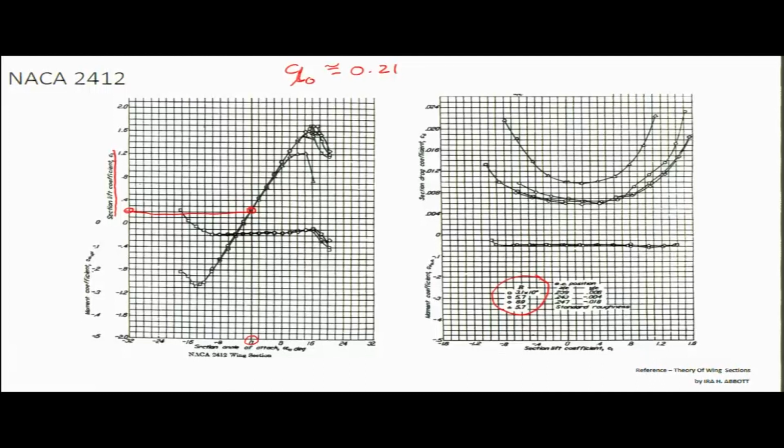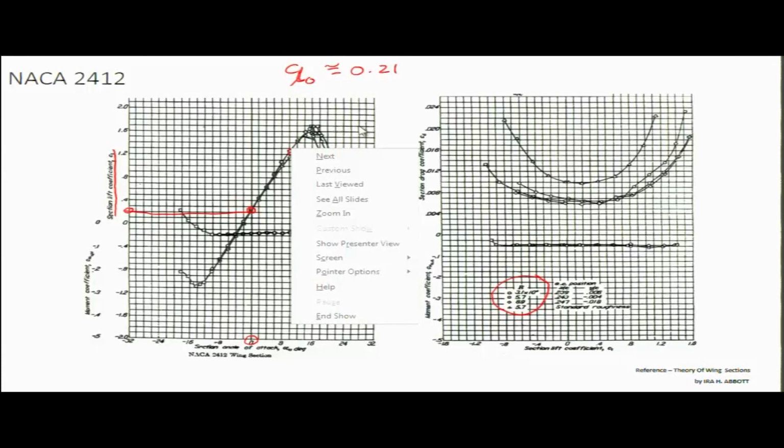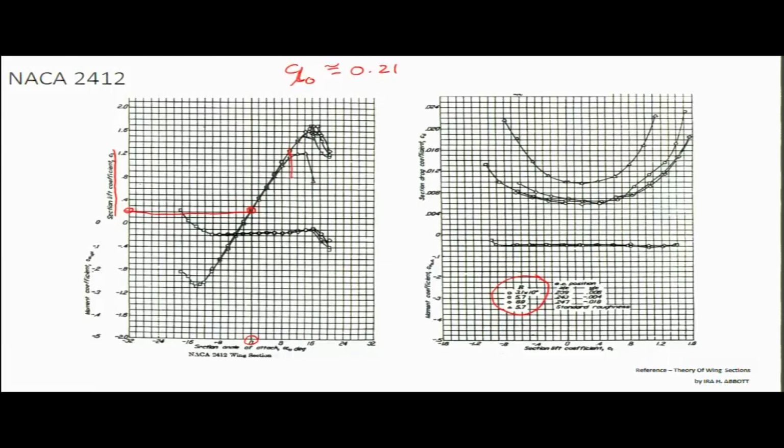And how to find out the CL alpha here, right? We will find out CL alpha while solving some of these examples. Now let us see how far this CL alpha is linear. For this particular curve, which is obtained by performing this test at 3 million Reynolds number, up to here it looks pretty linear, which is approximately 10 degrees angle of attack, right?